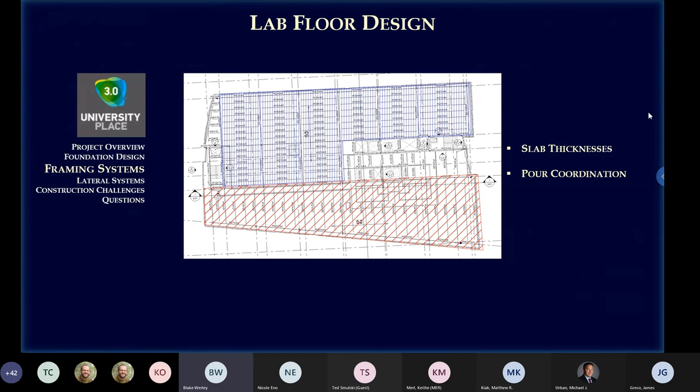We liked the idea of having one concrete mix for the whole floor to allow one concrete pour. But we also recognized that the lab spaces were wanting to be handled a little differently. So we considered normal weight concrete over the lab spaces and lightweight concrete on the office floor areas.